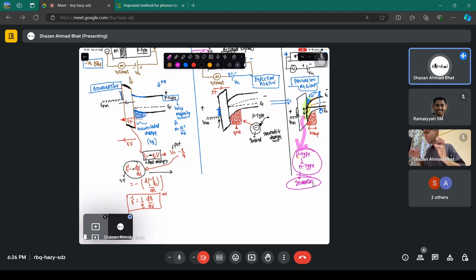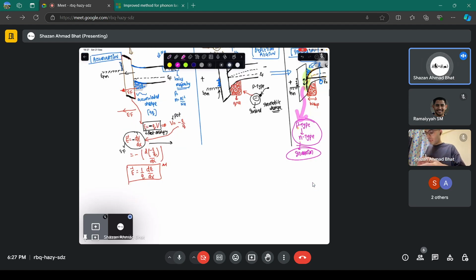But right now you are just studying MOS. Okay, you are studying MOS capacitors. And later on you will add something called a source and drain that will take these charges and the current will flow. Okay, right now here you are just inducing these charges. So this is what happens. These are the particular scenarios which are important for us.